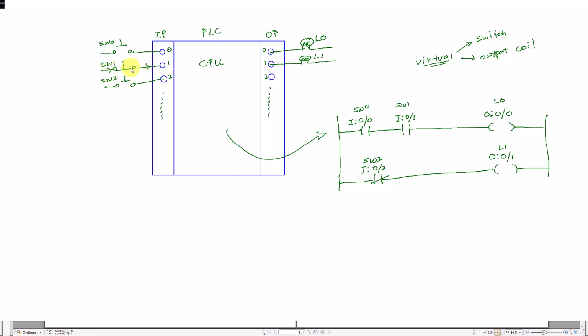So this actual current will energize digital input 1 internal LED as well as its digital input load. Since the LED 1 is energized, the corresponding virtual switch will be triggered.